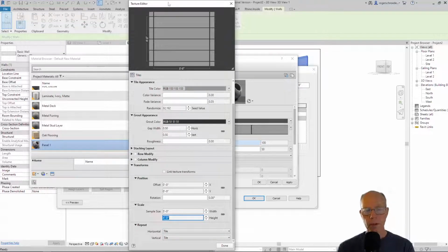Okay, so now if we just take a minute to look up at the tile, putting these numbers in this way has given us a tile that's going to be 5 feet wide. It's kind of the module of a curtain wall system. And then since this is saying 4 feet for 4 of these, which is the count that I set up for this, we're going to get 1 foot high tiles. So we want to do a few more things to this.